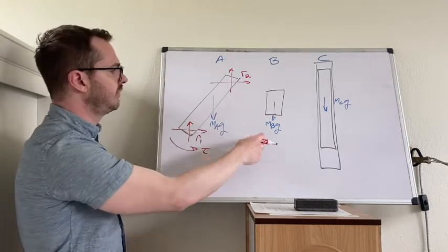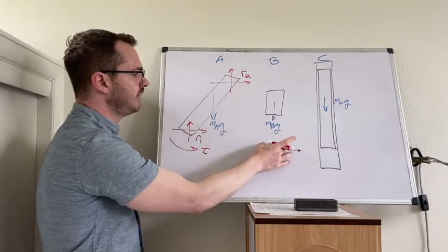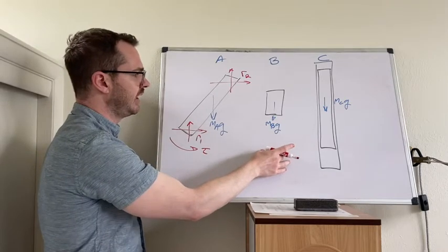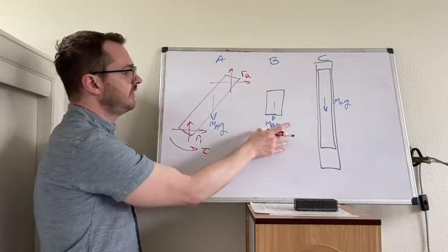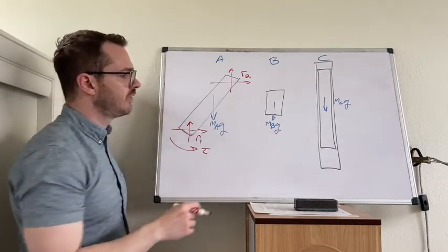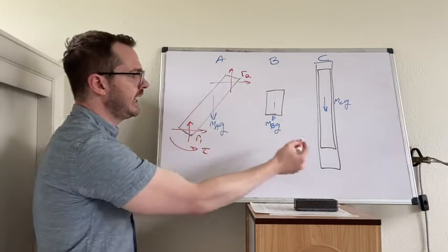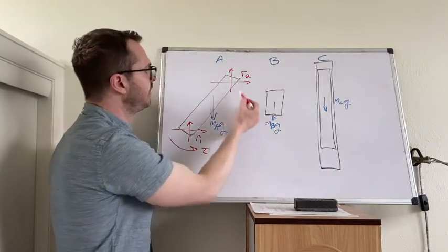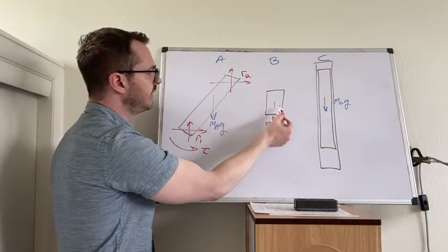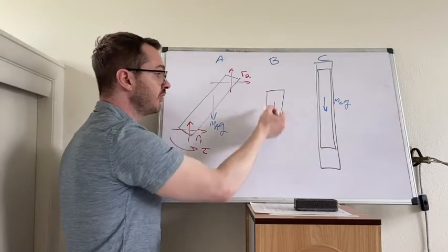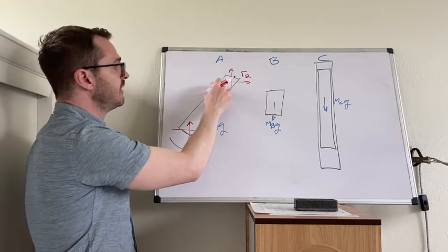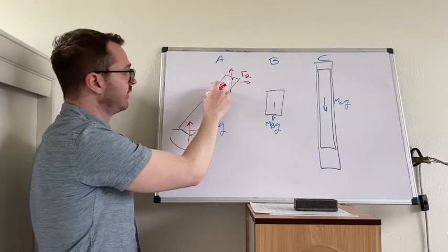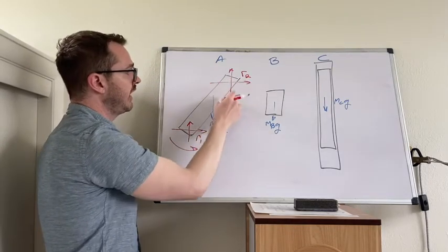So next, body B. We said that body B is the sliding block. Clearly gravity is acting on it. What else is acting on it? Consider that block B interfaces with both body A and with body C, right? There's a pin joint that is the interface between A and B, and then there is the groove that is the joint between B and C. There's reaction forces here at this pin joint. So look at how we define the reactions.